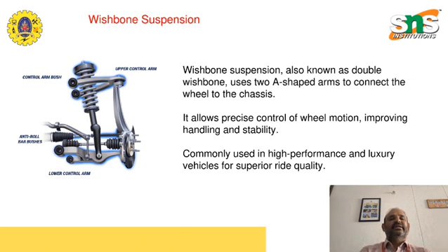Suspension affects ride and ground clearance. Adjustable suspension allows the vehicle to adapt to different terrains. Sports cars often use low and firm suspension for responsiveness. Off-road vehicles use high and flexible suspension for articulation. Suspension travel refers to the distance the wheel moves up or down. Longer travel is better for off-road use. Shorter travel suits